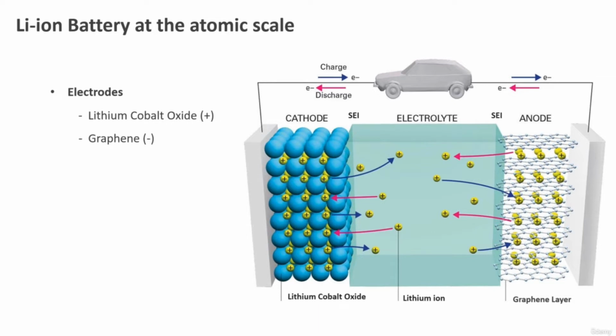The electrolyte only allows passage of lithium ions, positively charged lithium. Therefore, this charging requires the electrons to go through the external circuit. Only when the external circuit is closed via an application, an electrical current will run, driven by the lithium ions that migrate from the negative to the positive electrode. Under these conditions, the battery is discharging.